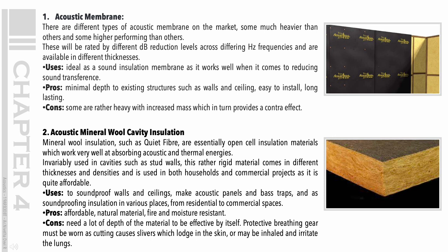2. Acoustic mineral wool cavity insulation. Mineral wool insulation, such as Quietfiber, are essentially open-cell insulation materials which work very well at absorbing acoustic and thermal energies. Invariably used in cavities such as stud walls, this rather rigid material comes in different thicknesses and densities and is used in both households and commercial projects as it is quite affordable.